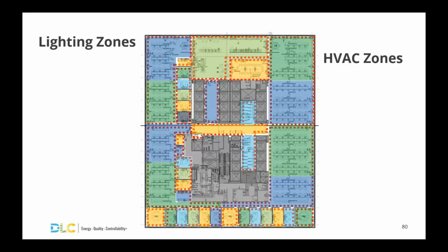So we have to have some harmony in the design there. That shouldn't be designed in silos. We ought to be thinking about how many sensors are there in the room? Which ones would affect which air handlers? How do they overlap? And what data can we get out of those? And how do we maybe use that for our sequence of operations?